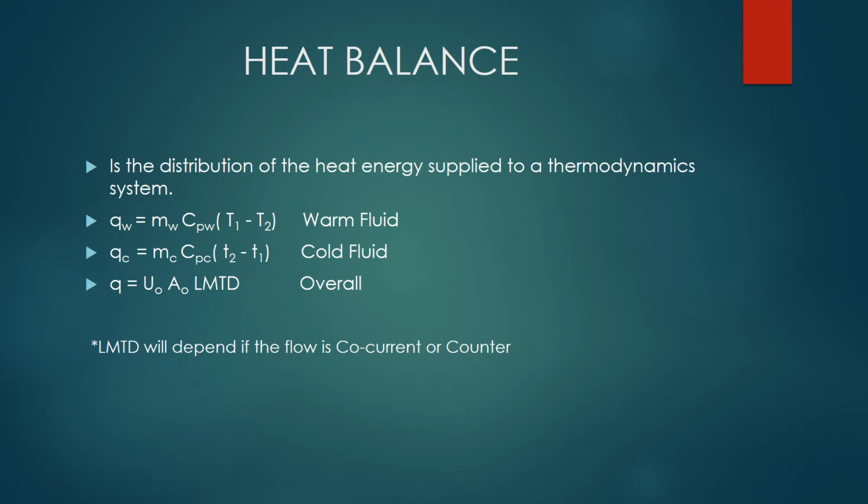To calculate the heat balance, you will need the mass flow, the heat capacity, and the temperature of both fluids, warm and cool. For the overall calculation, you need the heat transfer coefficient, the area, and the log mean temperature.